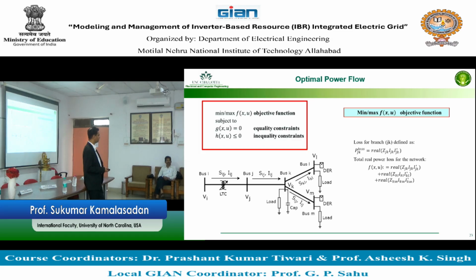It's a transformer connected on that branch, not a line. So for the transformer, we don't look at the losses because a transformer is considered very efficient. Even the distribution transformer can be low with respect to efficiency, I think 85%, 89%. Sometimes it can be higher; a power transformer is 99%. You don't reduce the losses inside the transformer, which is not possible, but you can reduce the losses through the line.